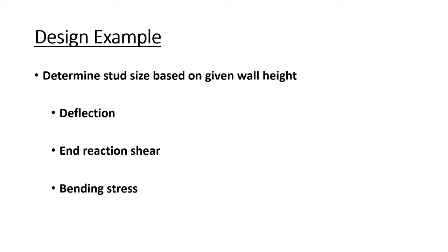The heights that a cold-formed steel-framed wall can span is based on an analysis that looks at the deflection of the wall, the interaction capacity of the framing members, and the bending stress of the steel stud as well. Heights are calculated based on these 3 considerations, and the lowest height attainable is then used for design of the wall. The deflection limit is based on the finished material.